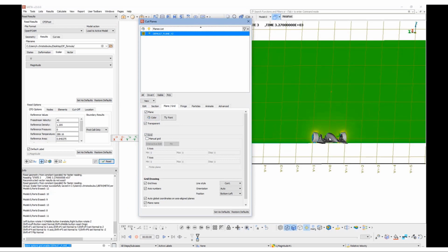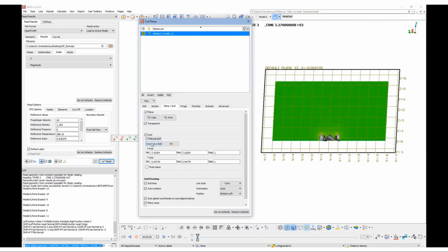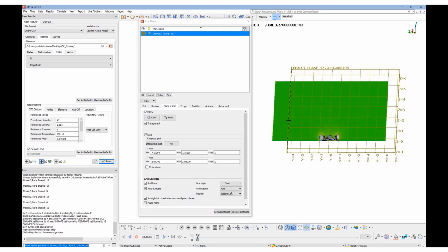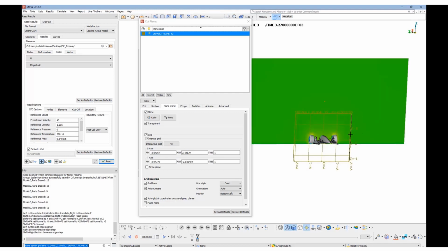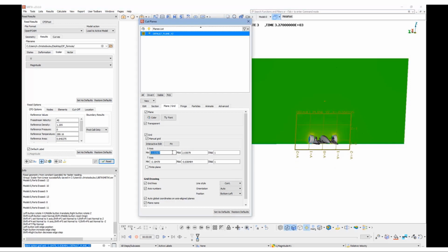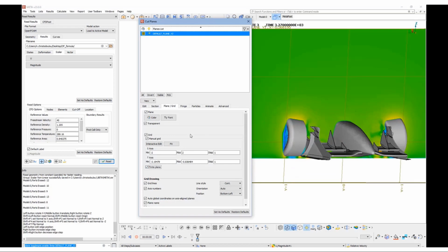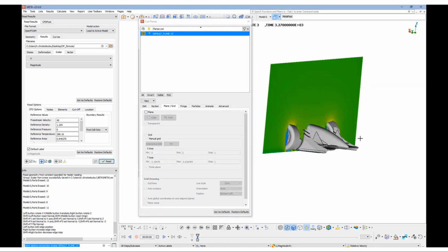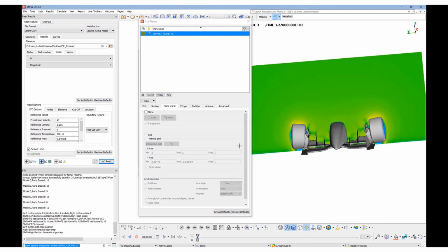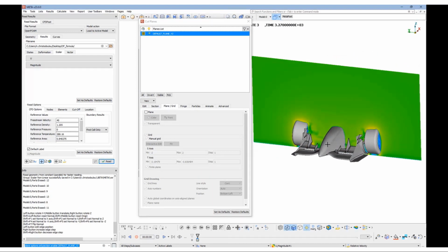And let's also change the height and length of the cut plane by activating the grid, which we can manually change. And then we will switch from an infinite plane to a finite one. In order to be precise, we can change the min and max values in order to have a purely symmetric cut plane. And we can activate the finite plane flag. Now it's obvious that the plane has been restricted at the boundaries of the grid that we modified.